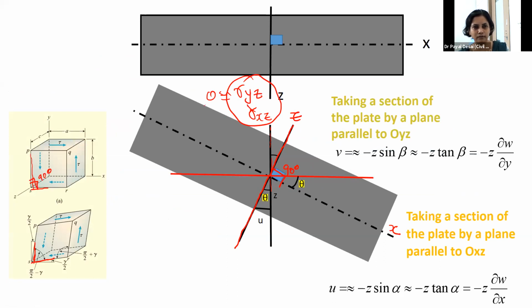And this is about thin plate theory. In our thin plate theory you are neglecting these two shearing strain components. There will be a shearing strain in the x and y direction that you cannot neglect, but because of this assumption of 90 degrees between the perpendicular line and the neutral axis of the plate, you can assume this reasonably, and this has simplified things so much. The significance of this assumption is so much that you can write your entire equations in the middle surface only.